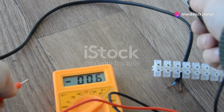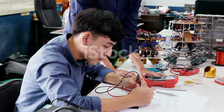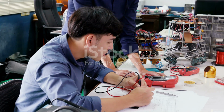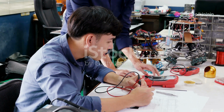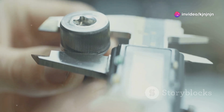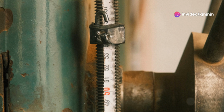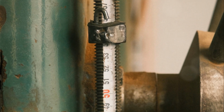Electrical resistance strain gauges are the most widely used type of strain gauge. Their popularity stems from their simplicity, versatility, and relatively low cost. These gauges consist of a thin metallic foil or wire arranged in a grid pattern. The grid is bonded to a flexible backing material, typically polyimide. This backing allows the gauge to conform to the surface of the tested material. When the material deforms, the metallic grid stretches or compresses, changing its resistance.